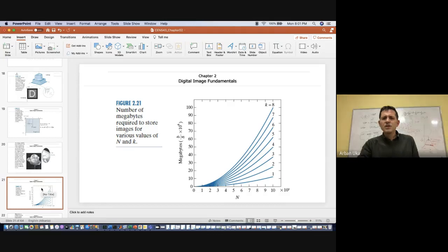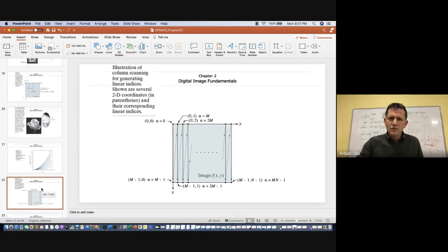If you have an image which is 1 bit, that means we have 2 levels of intensity, which are 0 and 1, so we have a black and white image. If you have 2 bits, that means we have 2 to the power 2, which is 4 different levels of quantization. So now we have a higher range of quantizing values, with intensity changing from really dark to really bright. With 3 bits, we have 2 to the power 3, which makes 8, and the pixel values go 0, 1, 2, 3, 4, 5, 6, 7.